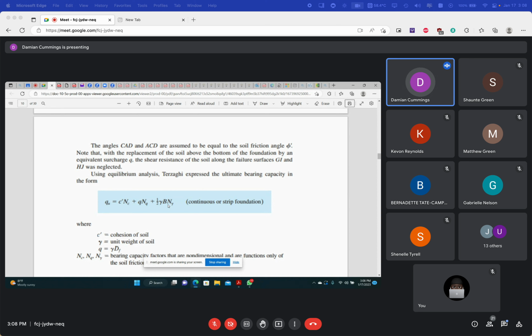We increase B in some cases so much that it takes up more than say two-thirds of the entire floor area. In that case, instead of making a wide strip, we just make a raft foundation. Good. And so the distribution of loading on the soil becomes much less.